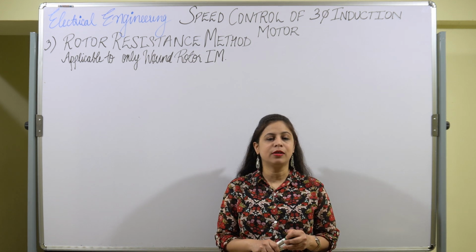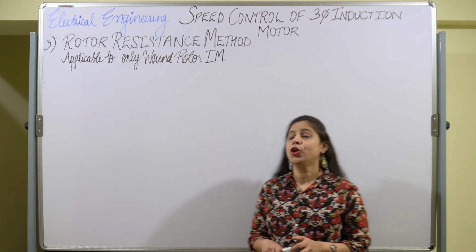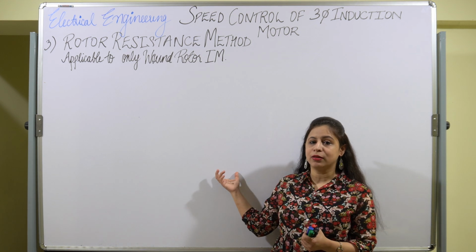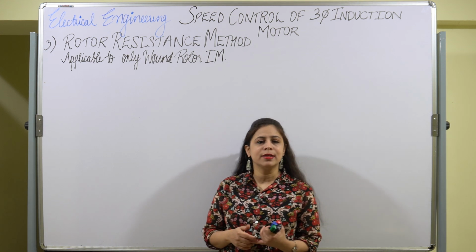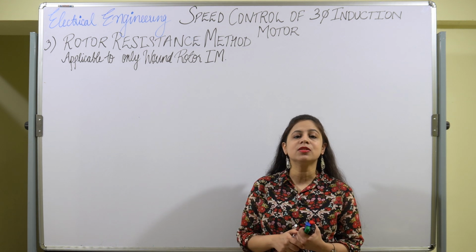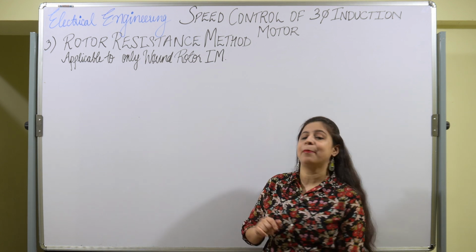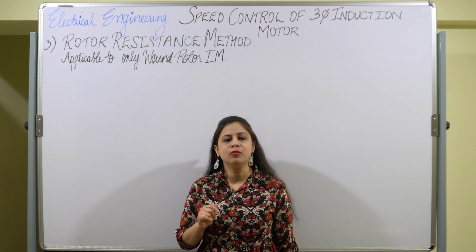The next method of speed control of three-phase induction motor is the rotor resistance control method. In this method we vary the resistance of the induction motor. But this type of method is only applicable to the wound rotor induction motor.